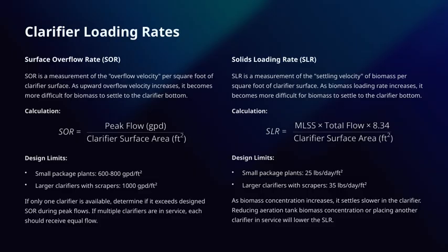It's important to check if, during peak flows, a single clarifier exceeds its designed SOR. If multiple clarifiers are in service, then each should be receiving an equal flow to prevent overload.